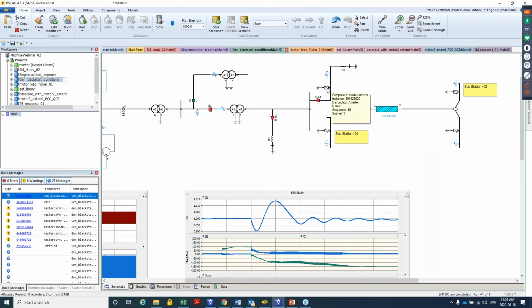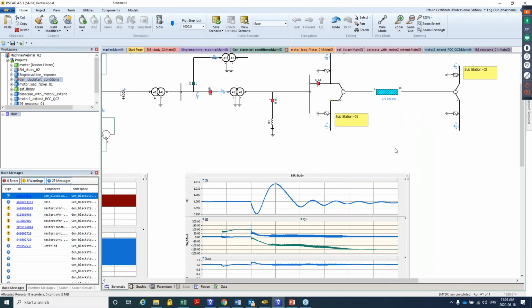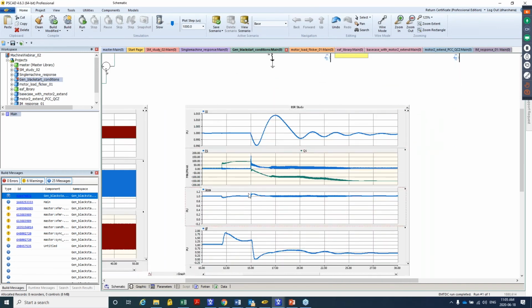We will discuss switching transients in a separate presentation, so I will focus on a more slow dynamic concern. When you energize the line without any loads, the long line is pretty capacitive. So reactive power would be injected back into the system by the line, right? Which would cause the RMS voltage to go up. So now the generator will have to control that voltage through its excitation.